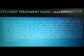Mechanical solids removal devices move as slowly as practical to limit resuspension of settled solids. Tanks are sized to give water an ideal residence time inside the tank. Economy favors using small tanks, yet if flow rate through the tank is too high, most particles would not have adequate time to settle and will be carried with the treated water.